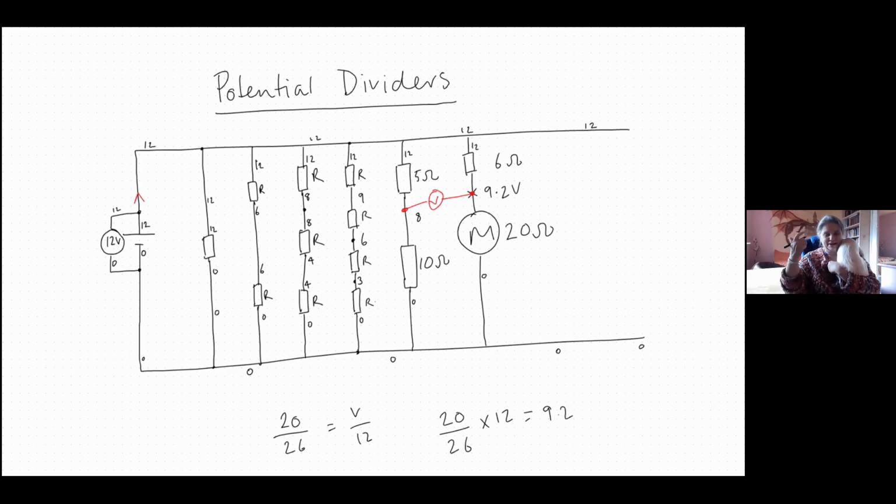Yeah, there you go. Okay, right, now what I was going to say is, every time you add a branch, more energy is drawn from the power supply. So the current through the power supply goes up. And in fact, the currents down the power rails go up as well every time you add in an extra branch. But have any of the resistances and any of the potential differences in the vertical columns, those parallel circuit segments, have any of those resistances or potentials changed because I've added in an extra vertical column?